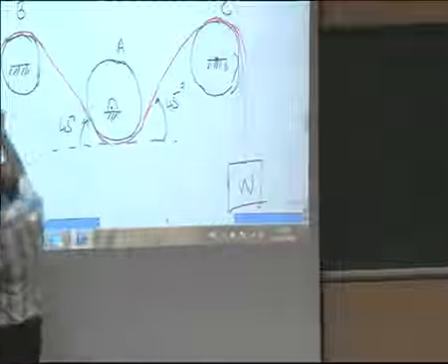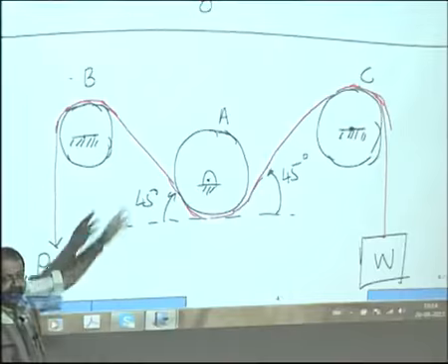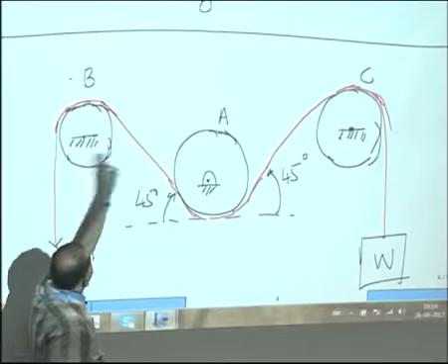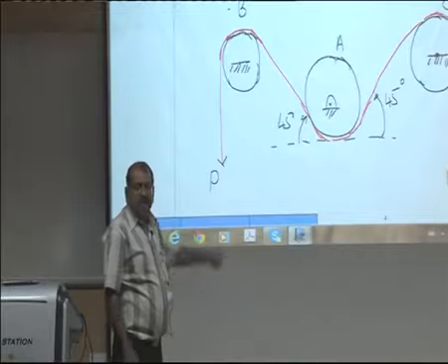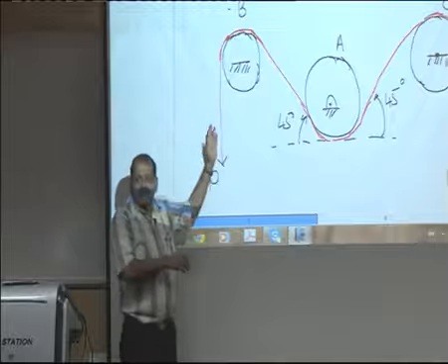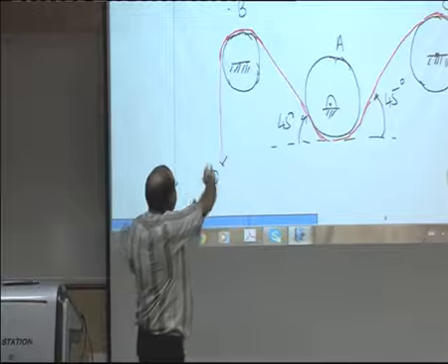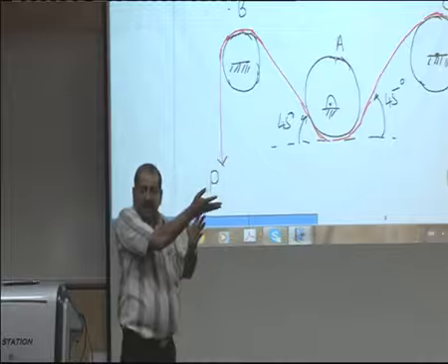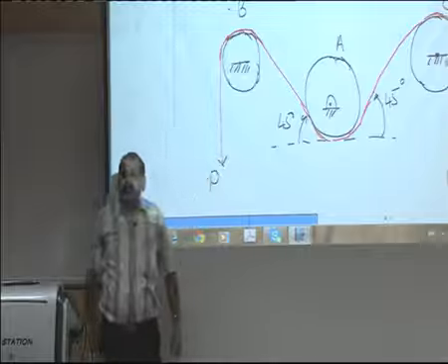Now, when I look at this, in which of these will tensions be greater? On the right side or on the left side? On this, once again we analyze that the tension on the left will be greater, because friction once again on the belt will be acting in the clockwise direction. So, therefore, where will the maximum tension in this belt come?